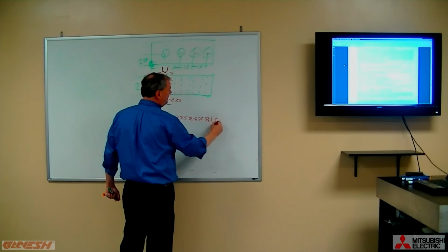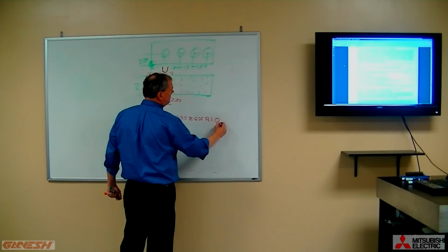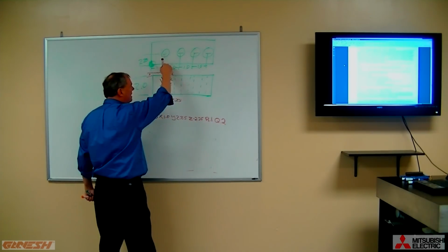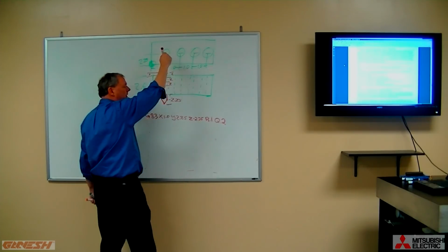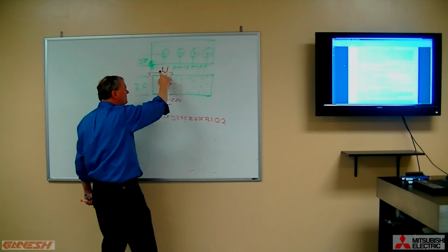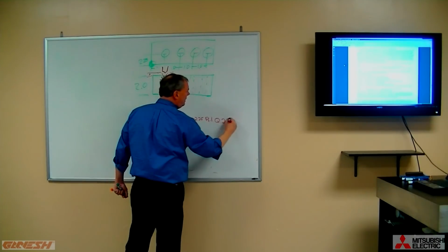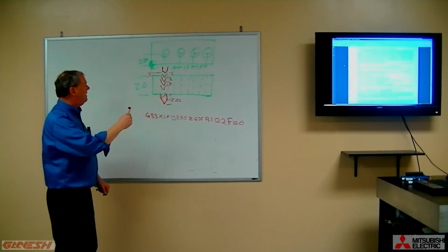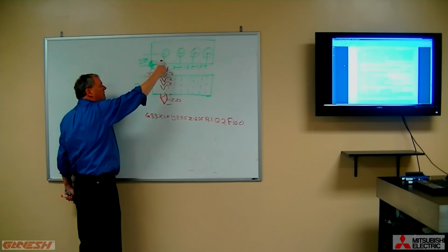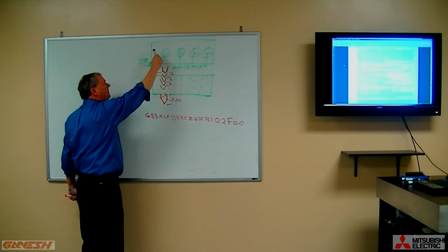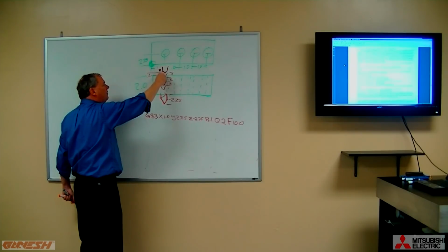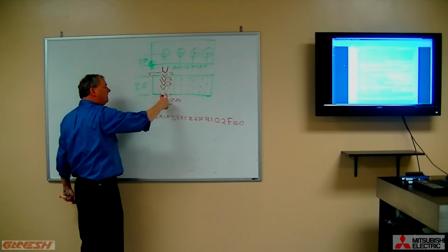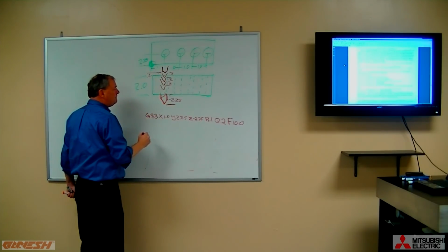And now all you need to do is add the number Q and tell it, I want it to go 200 thousandths of material before it pulls back out. So each time, cut 200 thousandths of material at a feed rate of 10 inches a minute. And now you are telling it to go down 200, come back out. Go rapid, and then another 200, come back out. Rapid back to here, go down another 200 and back out until it reaches its final depth.